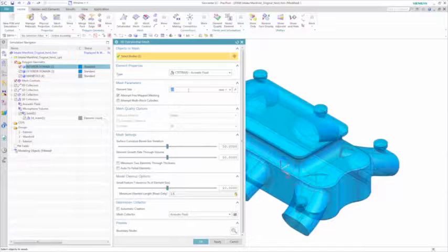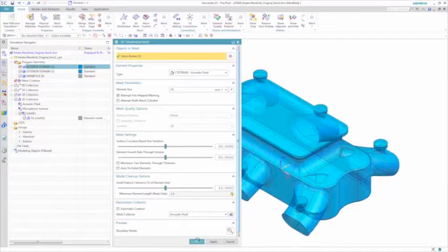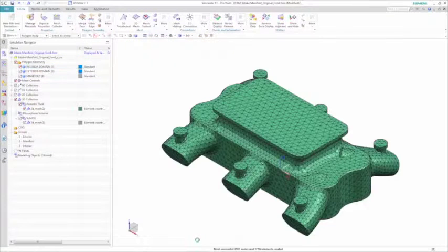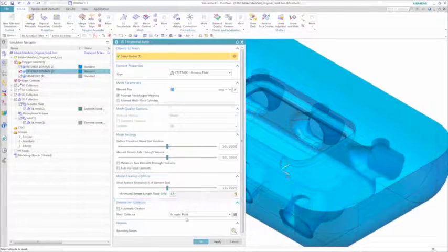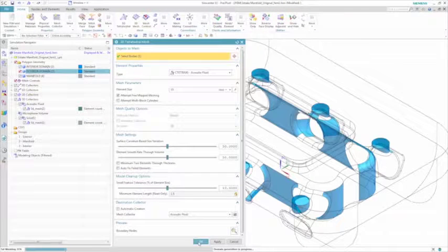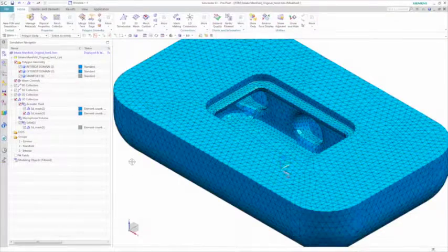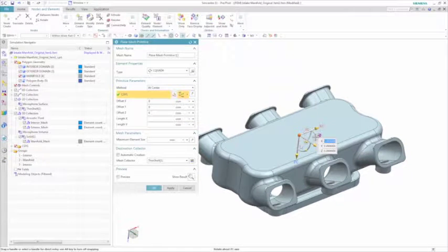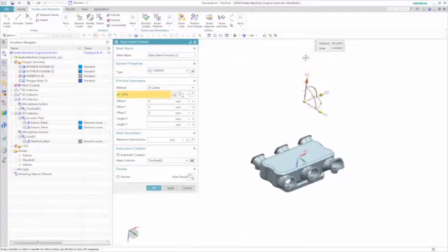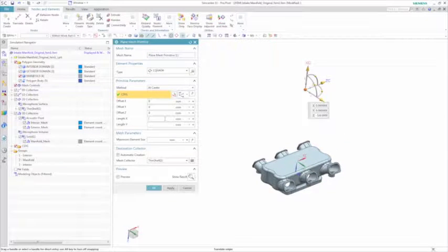NX Nastran, as the acoustic solver, can automatically work with otherwise incompatible meshes. Because we have selected a vibroacoustic solution, Simcenter 3D intelligently provides the right element types. For example, note that you can select an acoustic fluid type tetrahedral mesh for the acoustic bodies. Lastly, you need to define a mesh that will represent the microphone surface above the manifold. Once these meshes are defined, they can be assigned their material properties and you can add the loads and boundary conditions.